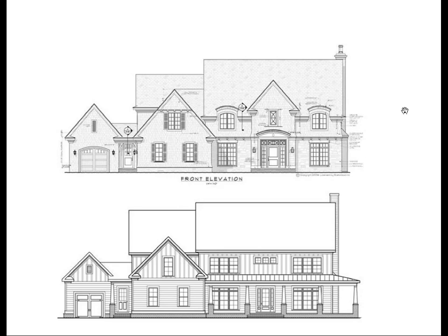Here's the final building elevation that we'll use to discuss. Notice that the eaves here in the front are a lot bolder, the lines that surround them, whereas the eaves in the back are a little bit thinner. Even though it seems like such a subtle detail, those line weights make a huge difference in terms of legibility of your drawing.